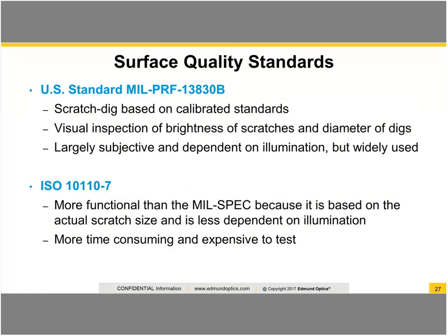The ISO 10110, the latest revision of that is 7. That's, in many people's estimation, more functional than the mil spec because it's based on an actual scratch size or dig size, and it's less dependent on illumination because of that. However, the downside of that is that it's more time-consuming to measure and therefore more expensive. So typically we see things specified on the mil spec.